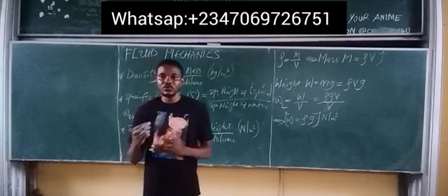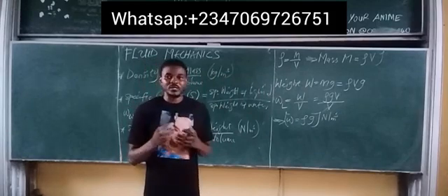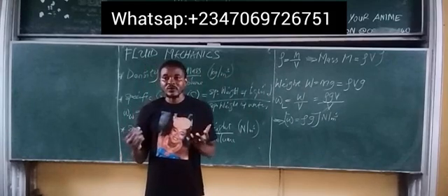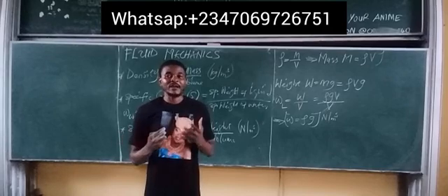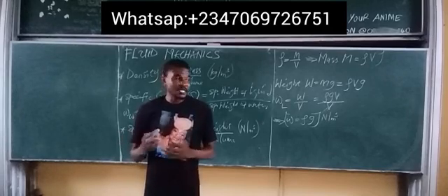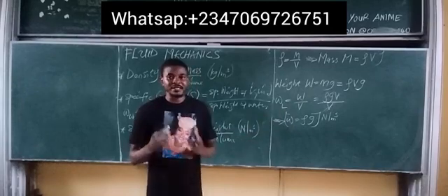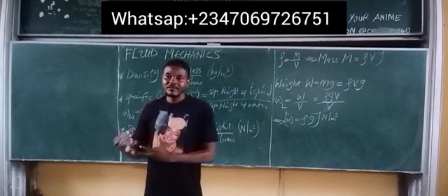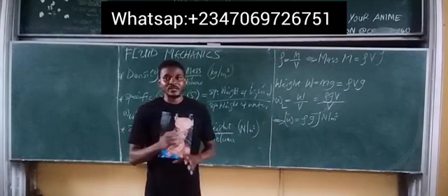So we can always use this alternate equation to find the value of specific weight. If any liquid is given to you, the density of the liquid is known, and of course gravity is constant, 9.81, we can always find the specific weight of that liquid given this equation. Simply density multiplied by gravity gives us the specific weight of every liquid.